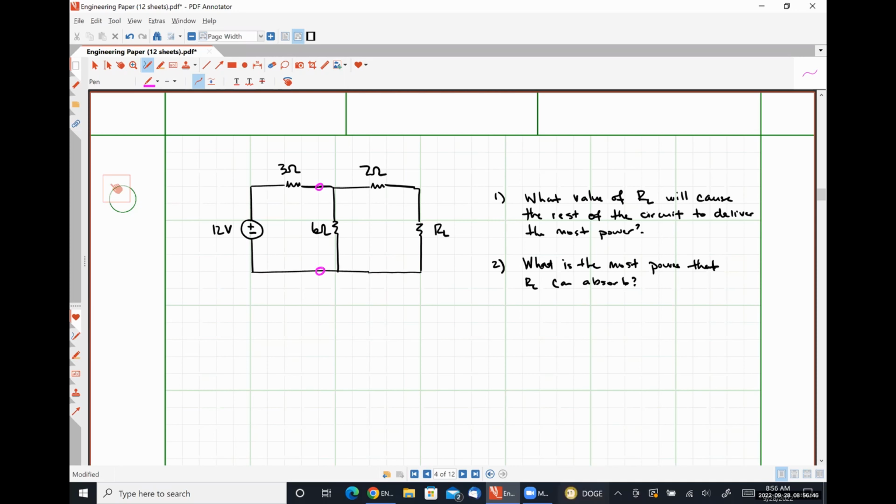So this transformation is governed by Ohm's law. So if I have 12 volts in series with 3 ohms, I should get 12 volts over 3 ohms in parallel with 3 ohms, right? So 12 volts over 3 ohms is 4 amps, yeah. And I need to put this in parallel with 3 ohms. All right. So what can I do now? Mason.